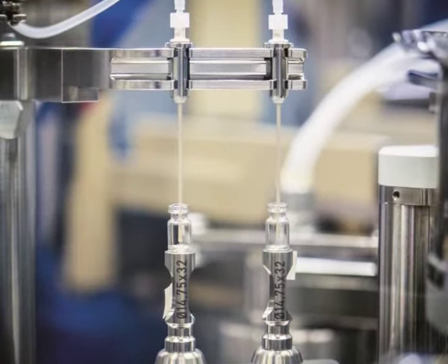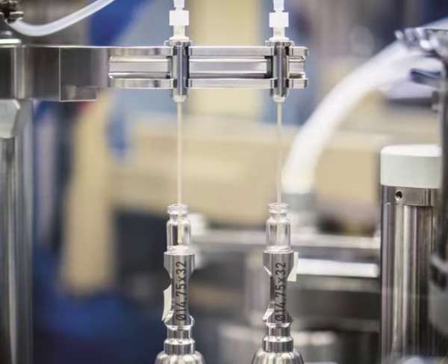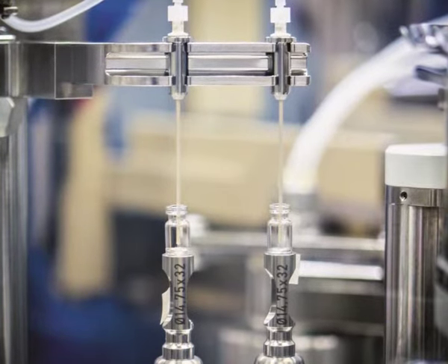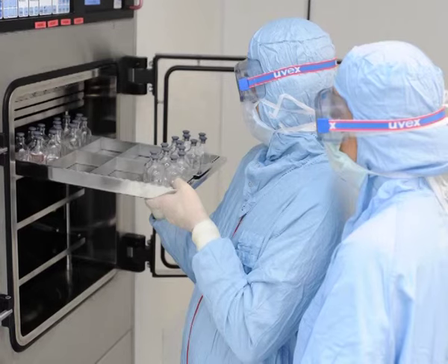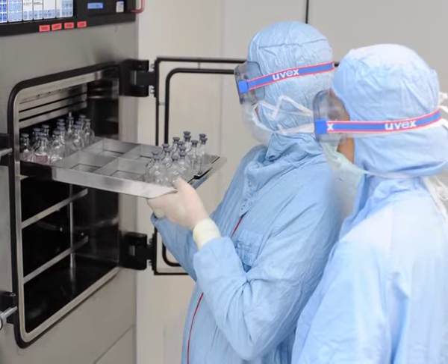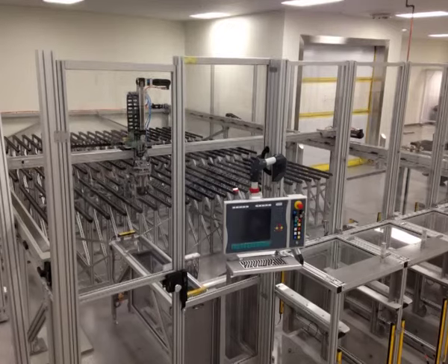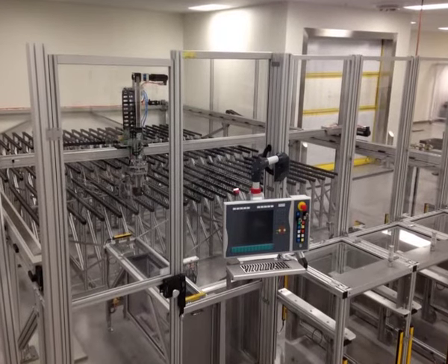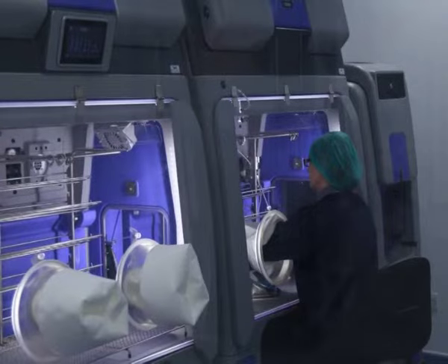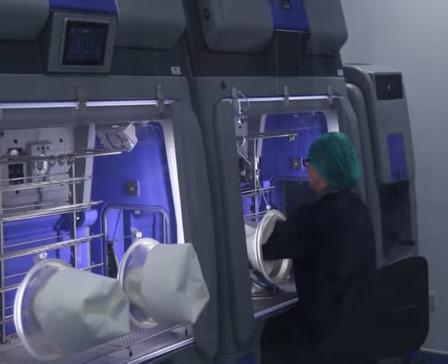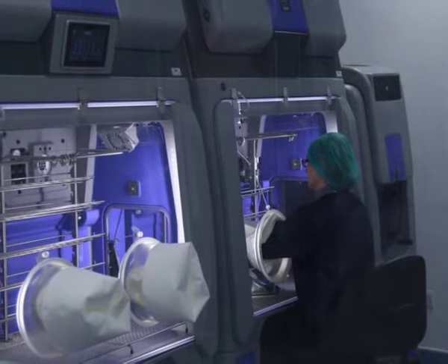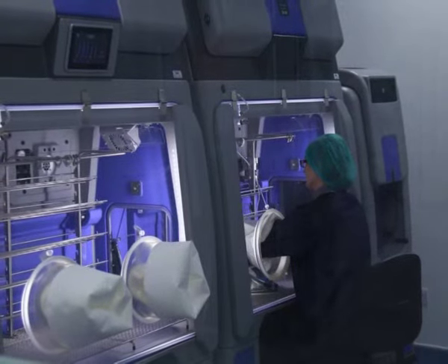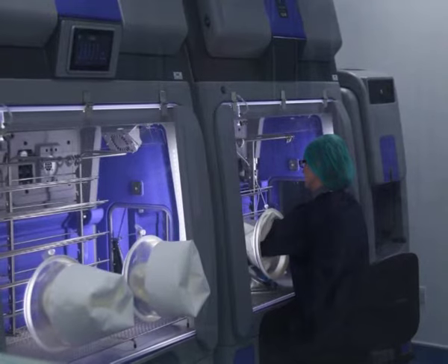Aseptic processes are designed to minimize exposure of sterile articles to the potential contamination hazards of the manufacturing operations, limiting the duration of exposure of sterile product elements, providing the highest possible environmental control, optimizing process flow, and designing equipment to prevent entrainment of lower quality air into the class 100, which is known as ISO 5. Clean areas are essential to achieve the high assurance of sterility.